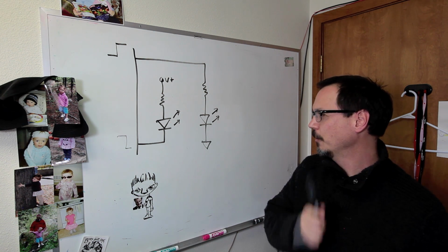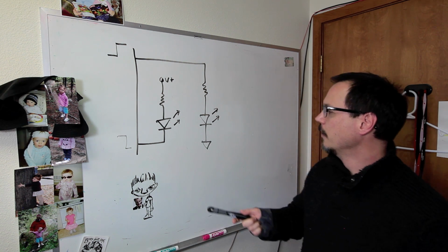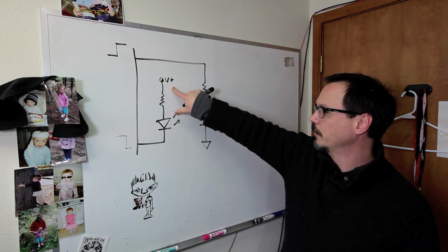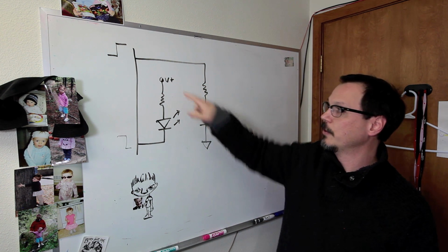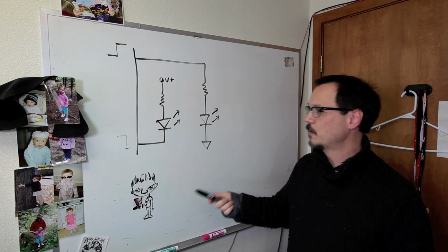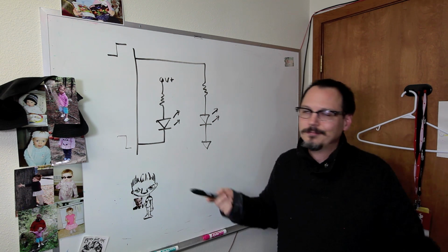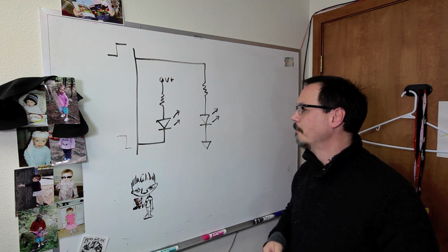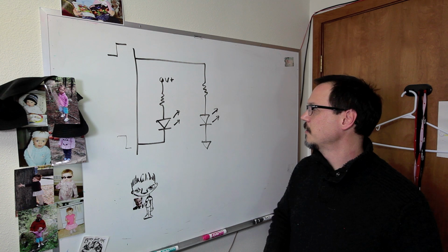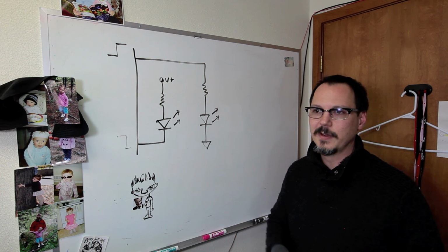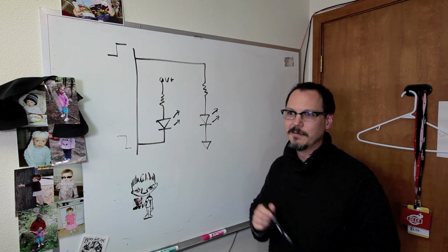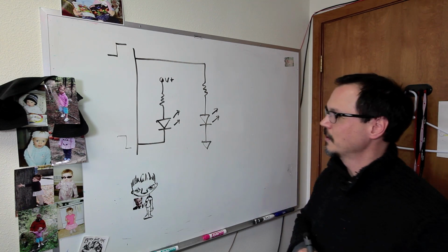Although it could be argued that if you're going to be working with a higher voltage, odds are you're going to be working with a higher current. You probably want to be switching that out with a transistor or something, possibly. But nonetheless, I like to stick to switching out ground. That's my fave. That's my convenience. That's my convention, and I'm going to stick to it.